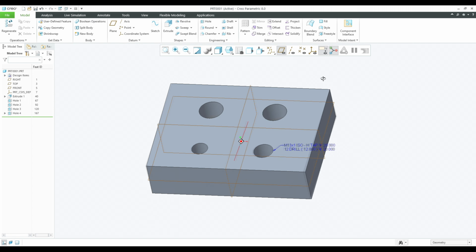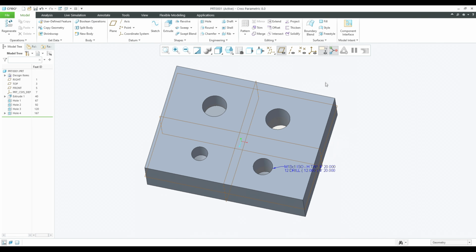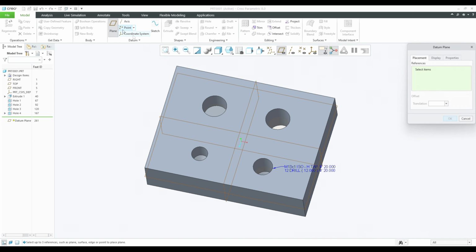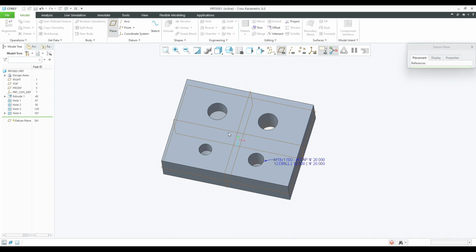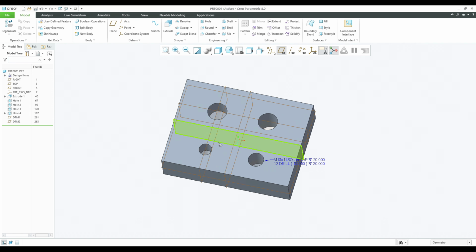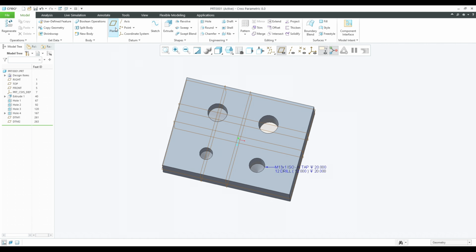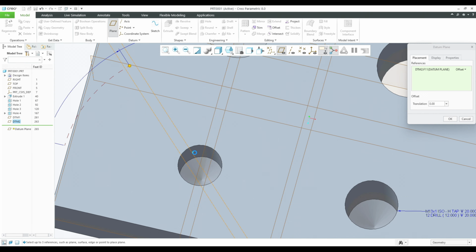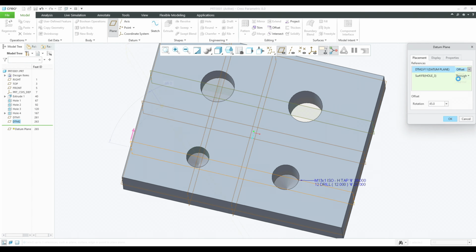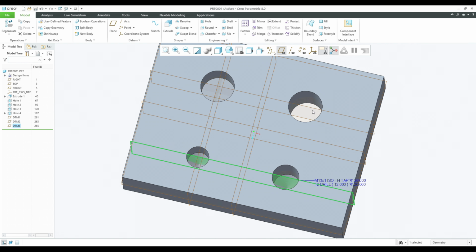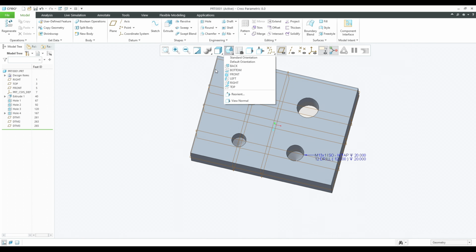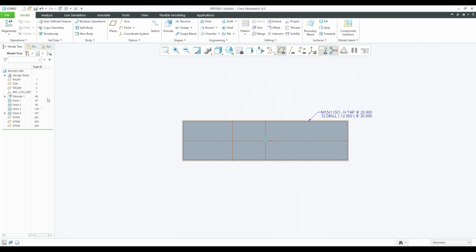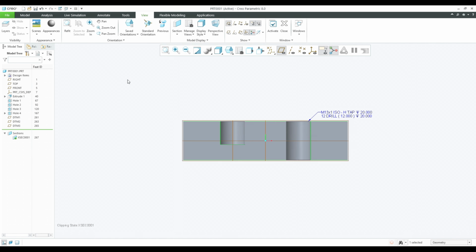So these are the four different types of holes I have created. Let me add a cut section view for everything, and I'll showcase how to view this. To add a cut section, I'm just adding planes here. I click on the front view, and I'm selecting datum 2, and I'll go to View. I'll click on the section, and it shows.